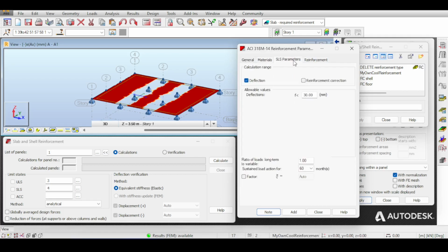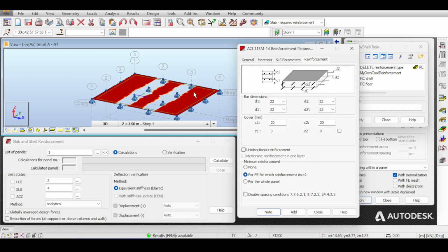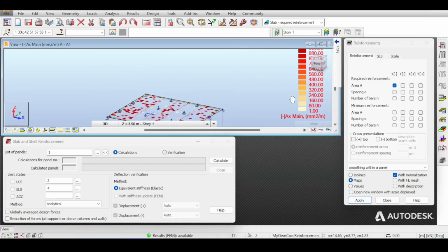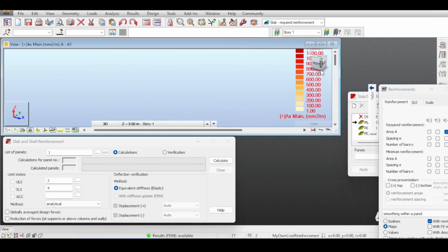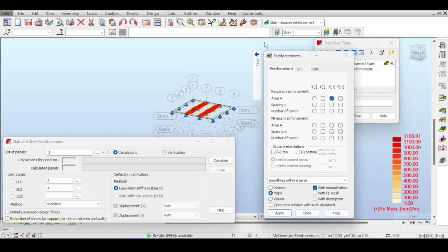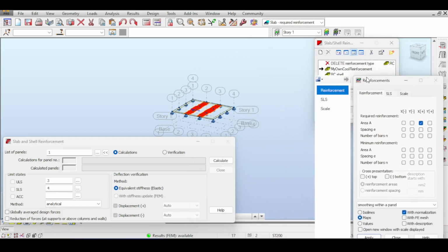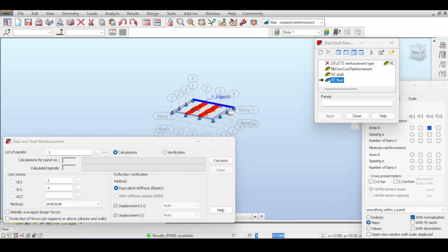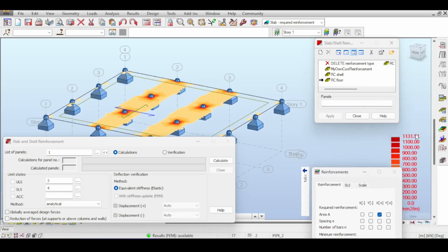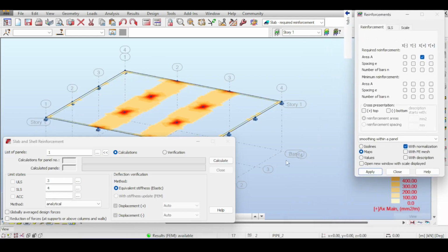This, I think, should have changed some of my reinforcement area steel, right? Let me check something very quick. Area steel here, you get the maximum of, to see the maximum steel was around 1189. That's oddly specific. I think this is the minimum steel. I think Robot is designing for minimum steel, does it? Let's take a look. Reinforcement floor. Let's click here. Yes, and let's calculate again. Did I apply this? Wait, let me just double check again. Yeah, see, it changed. Let me see. Yes, 1131. And it is behaving exactly as I want. Fantastic. Now, are we finished?